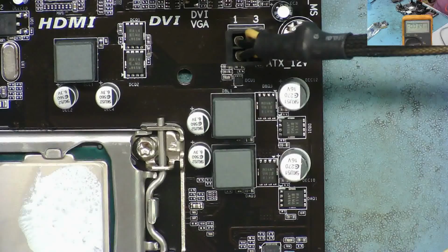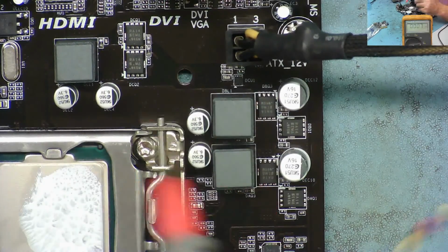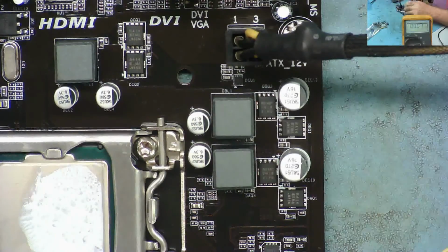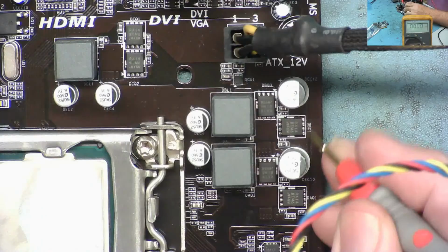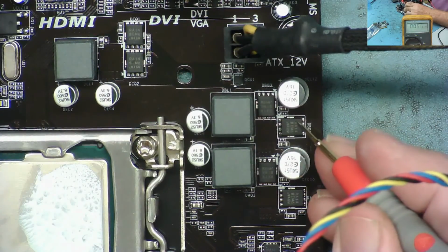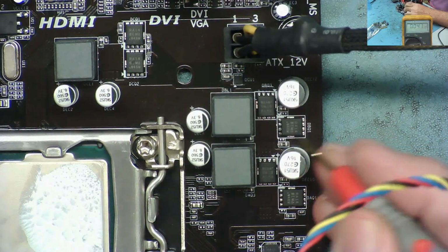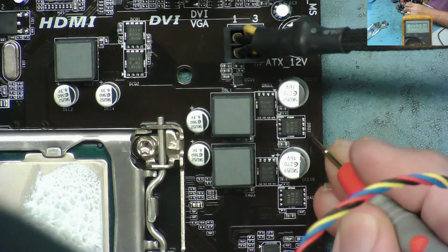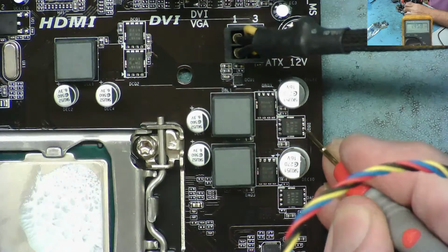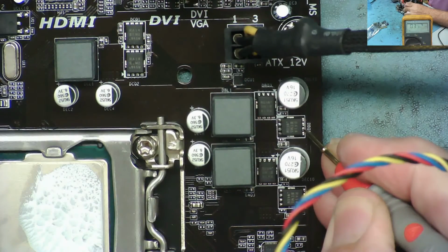Okay, we've got the meter where you can see it's on volts range. As I say, one place to check is just on the inductor coils by turning it upside down, but the other place you can check is on these MOSFETs. One side will effectively be source, the other side will be drain, and one of the pins will be a gate. So if we go on one of the middle pair here, we know it's not going to be the gate, and one side will be 12 volts. Let's see if it is this side.